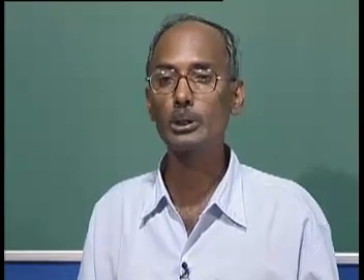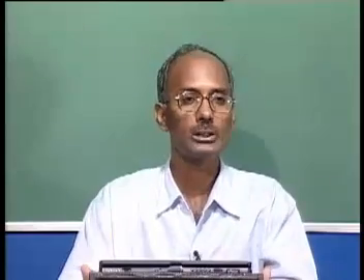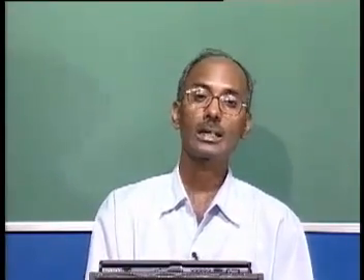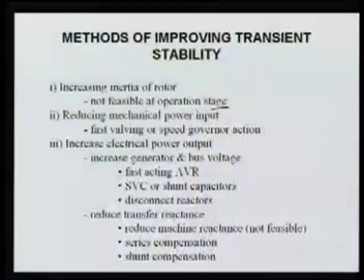This is not possible during the operational stage, because once the machine is installed and constructed and is going to deliver power, it is not possible to increase the inertia constant. It is only possible during the planning stage. When deciding which size of machine to install, you can change the inertia and go for a larger one, but you again have to consider efficiency and performance, which depends upon the economy and performance of the system. So this factor is not possible during the operational stage.